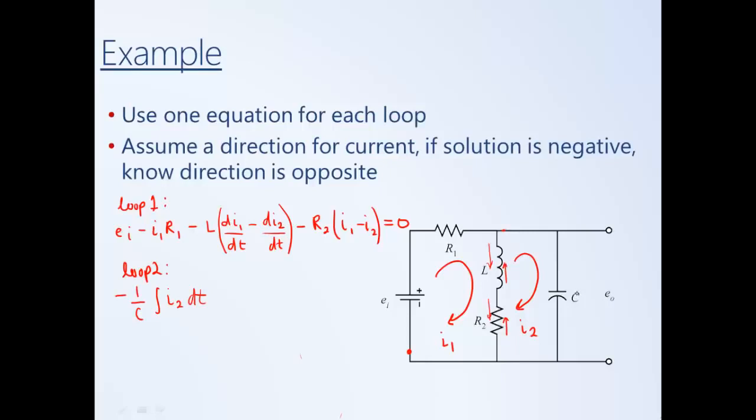And so some capacitors, the orientation doesn't matter. You can insert a capacitor either way into a circuit. With an electrolytic capacitor, the direction matters. And so you need to insert an electrolytic capacitor in a particular direction so that current flows in the correct direction through the capacitor, otherwise it will be damaged. This is something that we won't get into any great detail, but I just wanted to point this out in case you had a question about the difference in symbols.